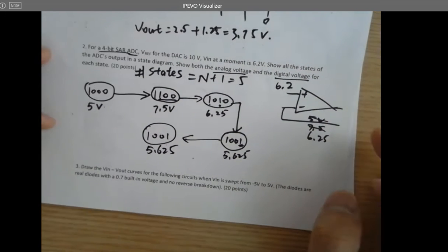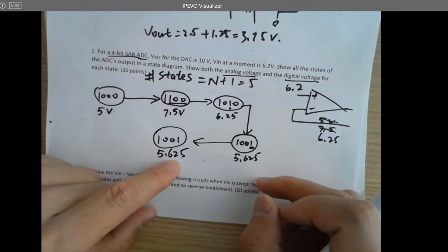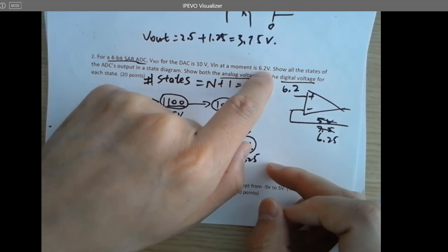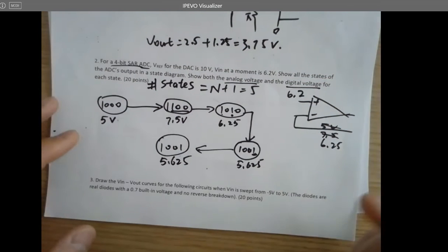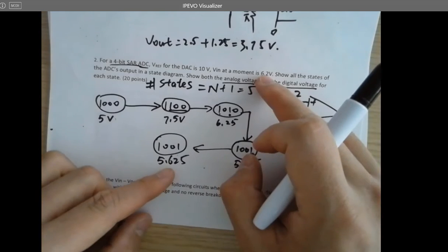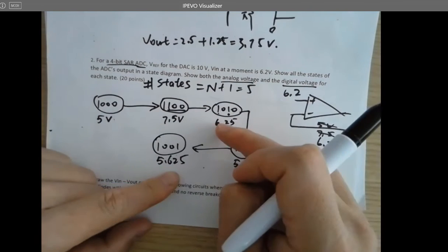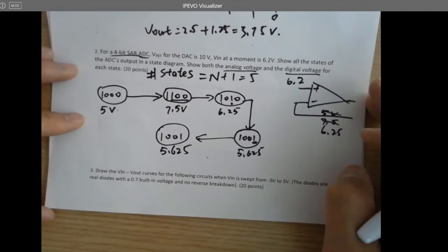All right. And keep in mind, the final converted analog voltage is always smaller than the input voltage, or sometimes equal to it. So if you see that the calculated value is larger than the input, it means something is going wrong in the loop. You just want to go back and fix it. That's how you can do a quick check with all the results.